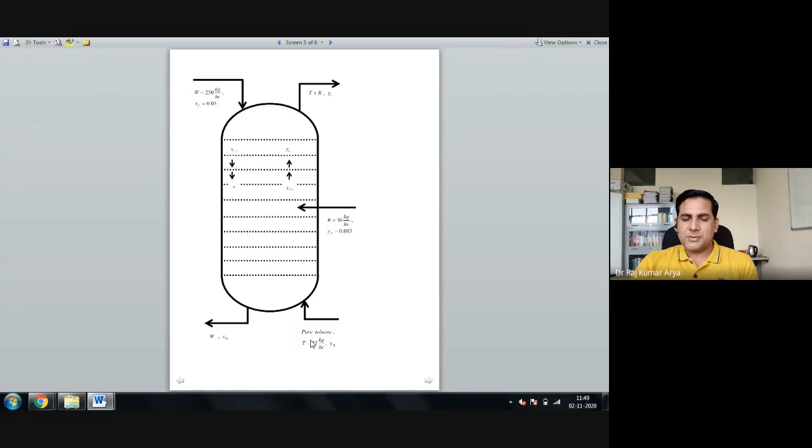You are putting toluene as the bottom material and passing it upward, and it will extract some amount of component from this feed. Whatever is coming here for the raffinate part, you are also pumping at the fifth plate, right? That's what they mention there, after the fifth plate.